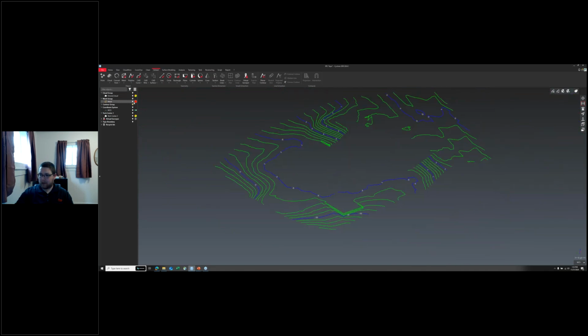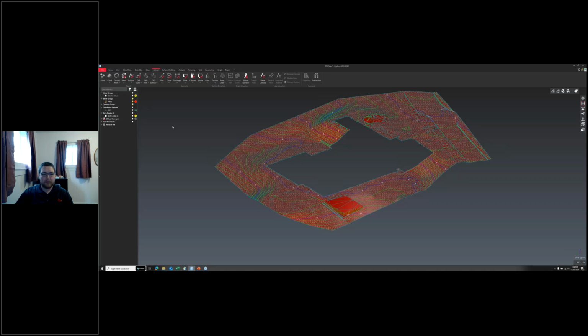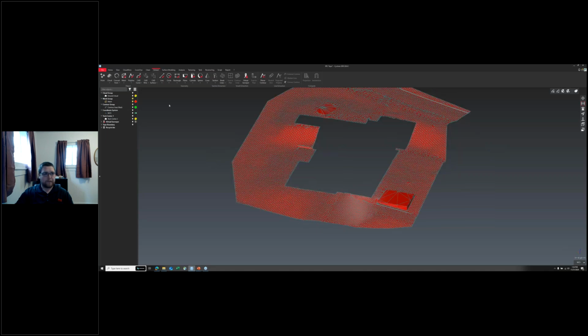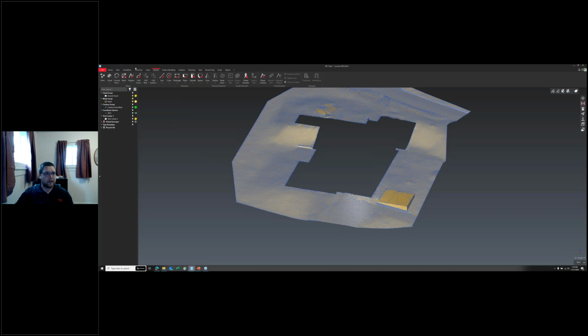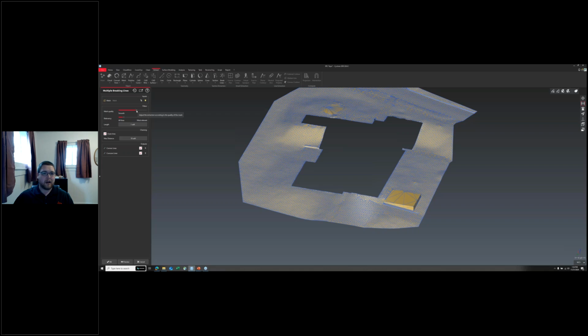One other quick tool to show that I didn't include in the outline is under the extract tab, where we have a different command for break lines. Even if you're watching all this and you still don't want to build your surfaces in 3DR, or maybe you want to build some in there but it still makes sense to build others in AutoCAD, things like your common rolling break lines, like rolling hills, maybe your top of banks and bottom of banks, are kind of subjective to extract out with what you need and where they're at.